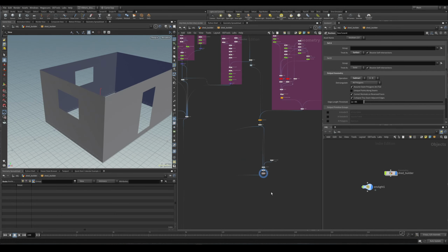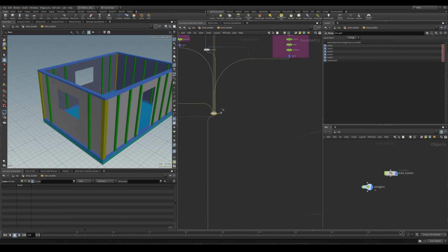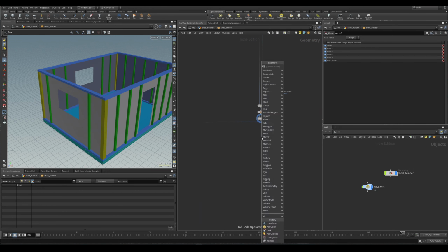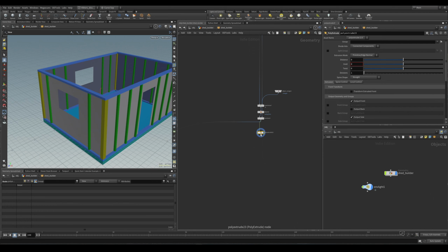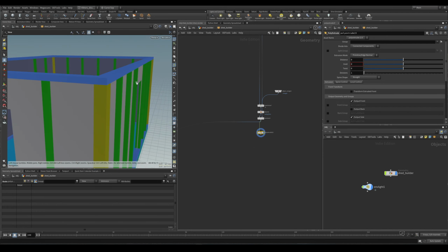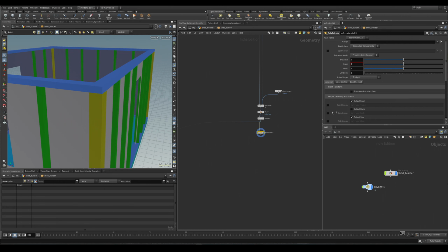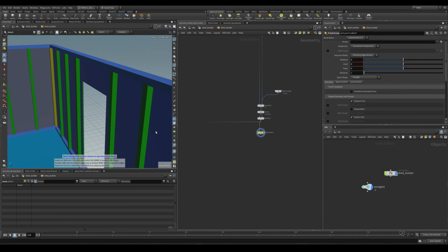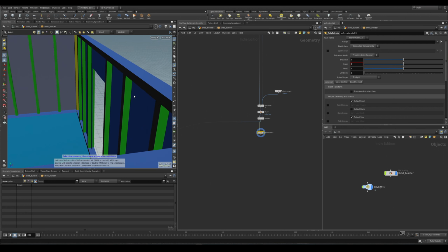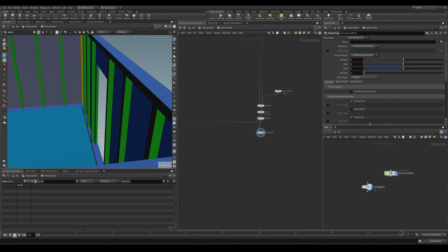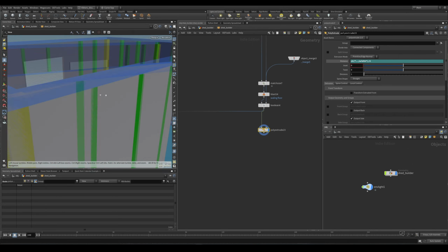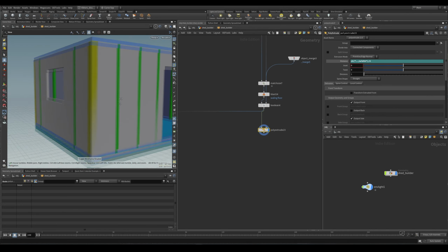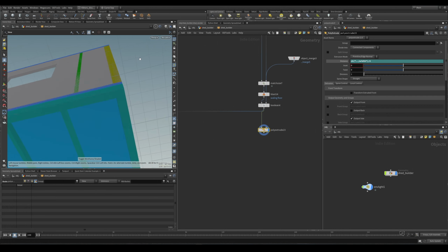And now let's make our walls fit our geometry. So I'm going to template this one, and let's actually put on a poly extrude. In this poly extrude, I want to make sure that my wall extrude is going to start from basically where our studs end. Right now our box is splitting across our studs. So just copy the width of our studs, and for extrude just paste inside here and divide it by 2, like that. And now our wall is intersecting with this all very nicely.